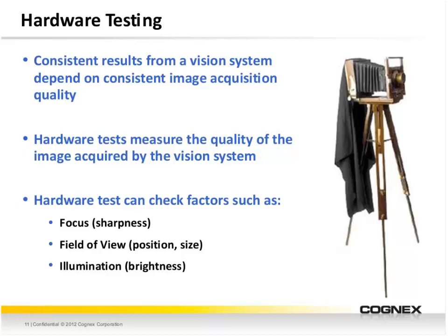And then lastly, something we all probably heard a lot about at customers with field of vision installations is if the illumination's off. So if the lighting has changed or they didn't mount it in the correct location for whatever reason, then you can put in maybe some checks on brightness or contrast to look for those type of features.